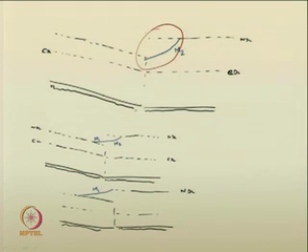Here, in this situation, the M2 curve in channel 2 has a positive slope, the water surface slope is positive here. So, theoretically not possible, because dy by dx is positive there. So, it is theoretically not possible. So, this portion does not exist, such a water surface profile will not exist.